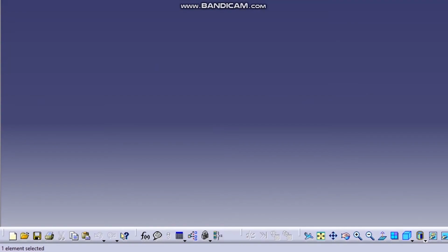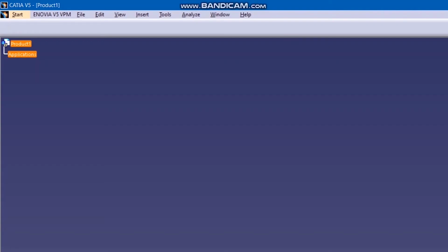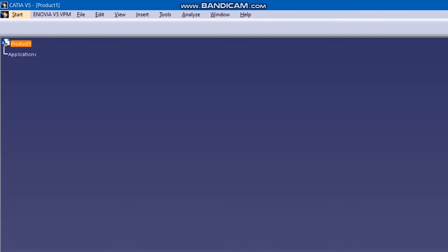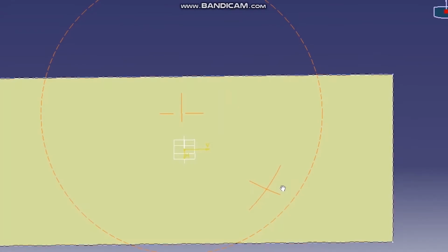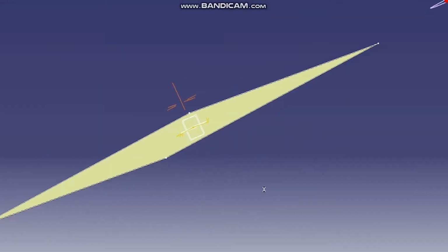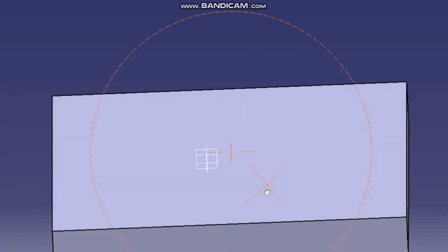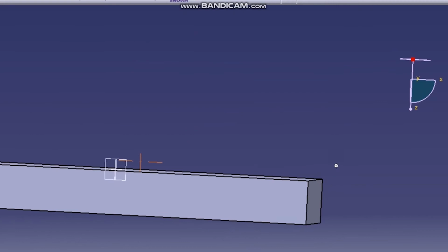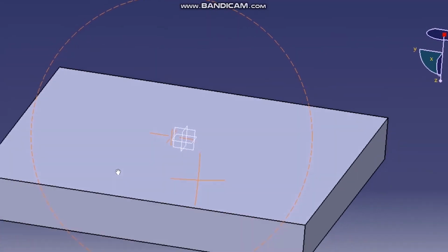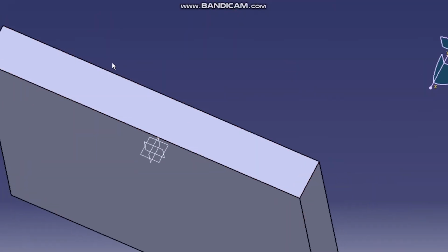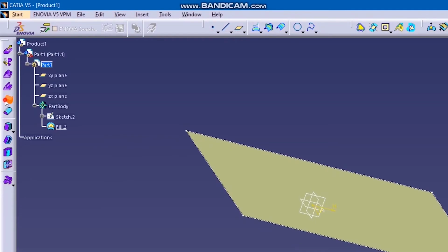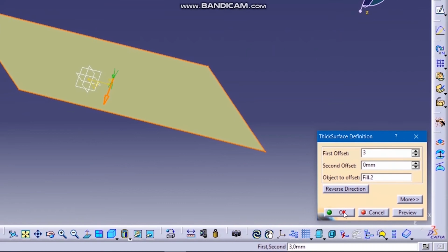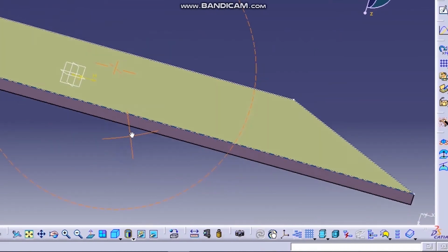I'm using the CATIA V5 R19 version of the software. We'll be learning the generative shape design workbench. In this workbench, we mainly deal with thin, negligible-thickness sheets which can be molded as per your requirement, unlike part design, where we dealt with thick, defined solid objects whose thickness we defined. In generative shape design, after drawing a required shape, we add thickness according to our requirement, say 1 mm, 2 mm, 3 mm, whatever it may be.